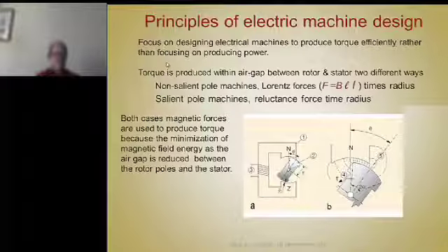This was evidenced by a famous paper by two IBM guys by the name of Lawrenson and Chai. They were advocates of reluctance machines for step motors because they didn't require any magnets, and IBM didn't want to use magnets in the step motors they used for their printers and a lot of their computer peripherals. Remember, they were the leaders in computers for many years, and they made all their own peripherals. They discovered that a reluctance machine could compete with about anything if you drive the circuit into saturation around the air gap. It essentially doubled the torque output.